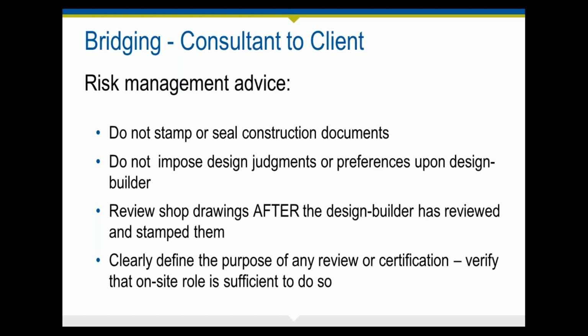If the client wants you to review shop drawings or other submittals, this should be done only after the design builder has reviewed and stamped the shop drawing. And it should be made clear that the independent design professional is undertaking such review solely for the benefit of the client. You should not communicate with contractors or subcontractors on any aspect of the project so that there's role clarity about your responsibilities.